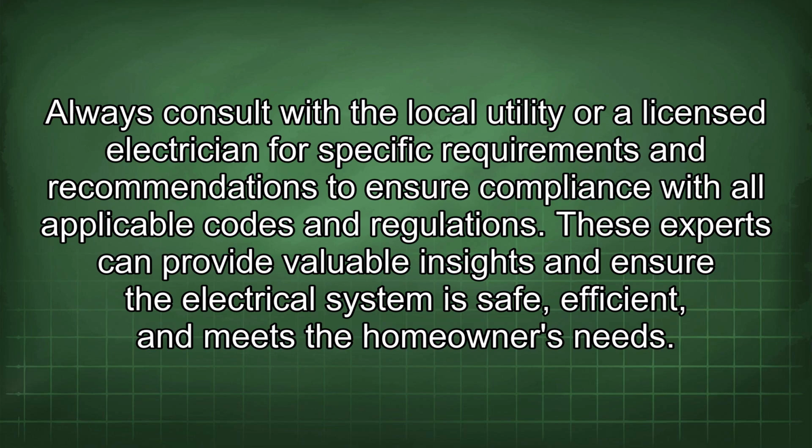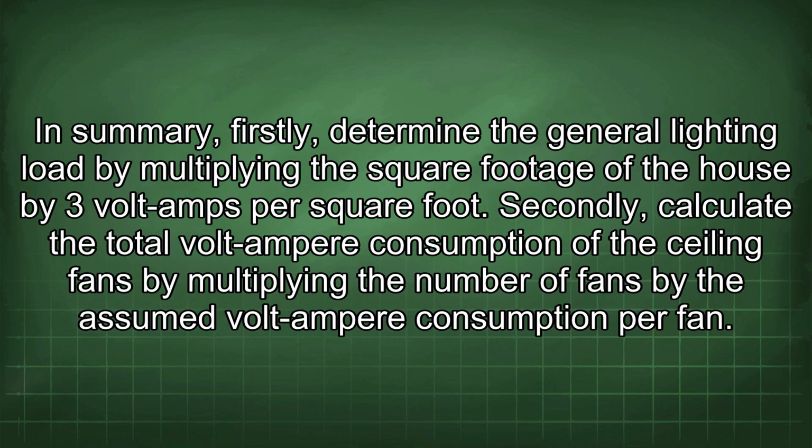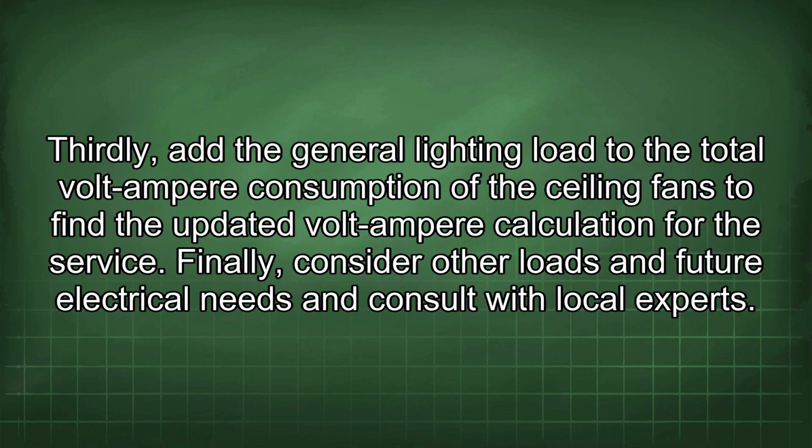homeowner's needs. In summary, firstly, determine the general lighting load by multiplying the square footage of the house by 3 volt-amps per square foot. Secondly, calculate the total volt-ampere consumption of the ceiling fans by multiplying the number of fans by the assumed volt-ampere consumption per fan. Thirdly, add the general lighting load to the total volt-ampere consumption of the ceiling fans to find the updated volt-ampere calculation for the service. Finally, consider other loads and future electrical needs and consult with local experts.